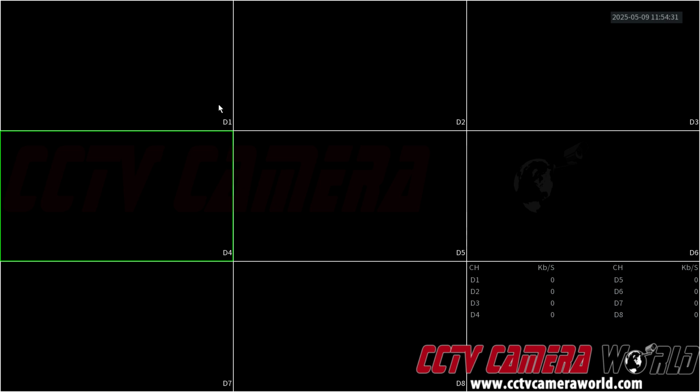It's almost like having an FM radio with a radio station, and if you're traveling between cities, sometimes those radio stations use the same frequencies, and you may hear crosstalk between those two frequencies. When there's crosstalk for wireless devices or Wi-Fi devices, it may cause intermittent connection issues or cause those cameras to drop entirely. So to fix that, again, we're going to go into the NVR and set it to a specific channel and show those channels.